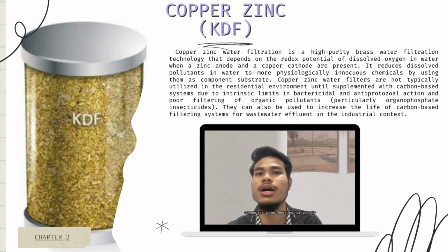Copper-zinc water filters are not typically utilized in the residential environment unless supplemented with a carbon-based system due to intrinsic limits in bactericidal and antiprotozoal action and poor filtering of organic pollutants. They can also be used to increase the life of carbon-based filtering systems for wastewater effluent in the industrial context.